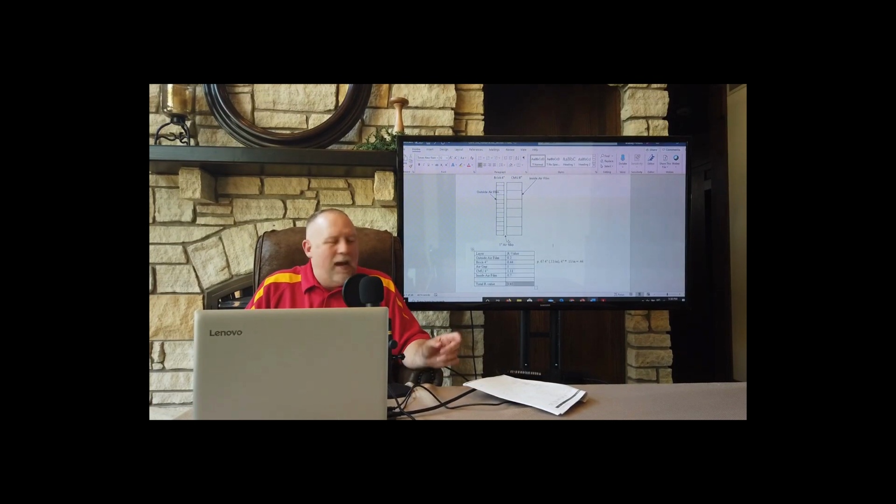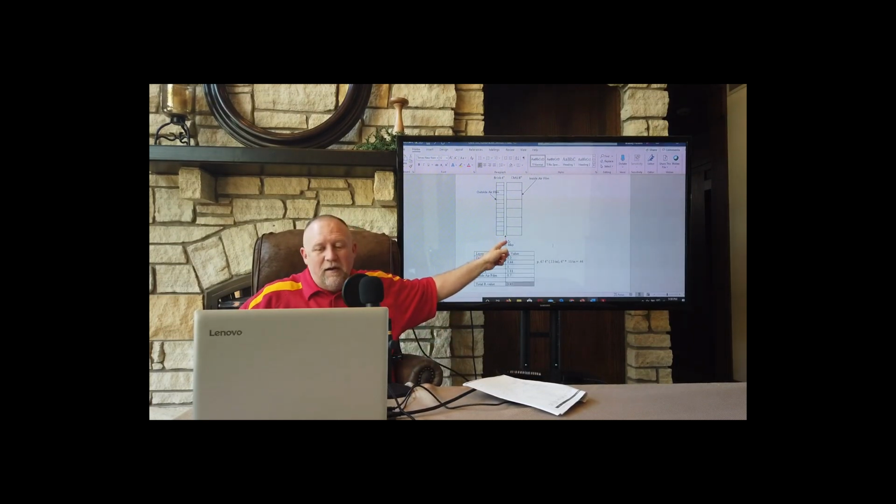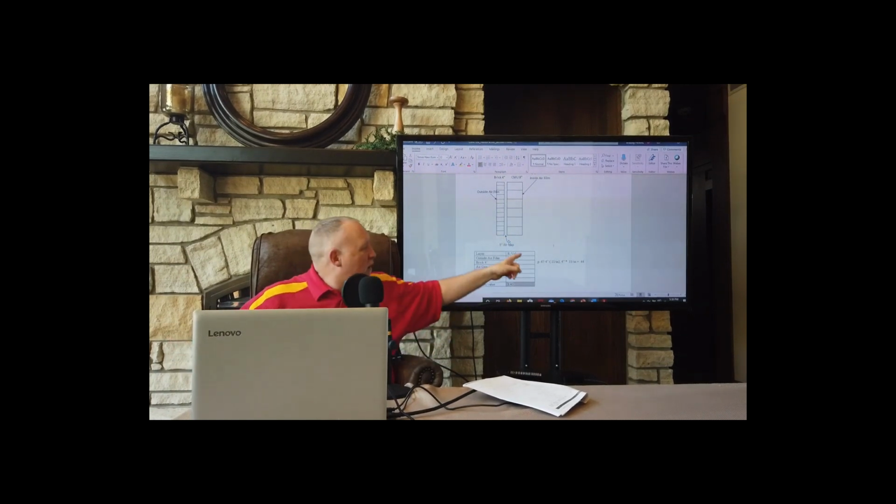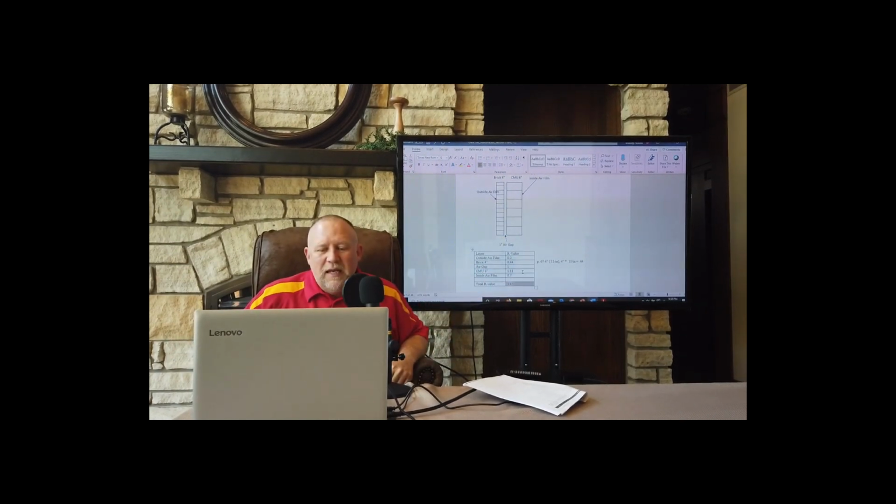Next is the air gap. Okay, air gap right here. It's a 1-inch air gap. Even if it was a 2-inch or a 3-inch air gap, we're going to give it an R value of 1. Next is the 8-inch CMU, concrete